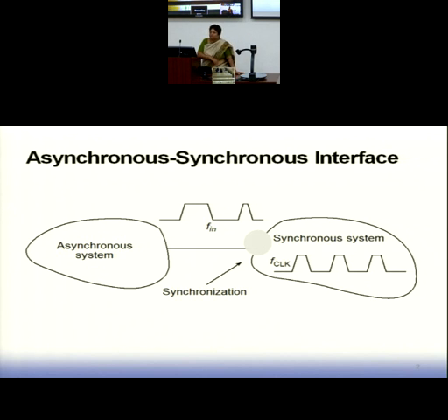See, we normally talk of a synchronous system design. That is what normally is designed also. So it so happens that sometimes you get an input from a keyboard, which is asynchronous, which can come at any point of time, which is not aligned to the clock edge. Now this can come and it has to go into the system and should lead to a valid system output.